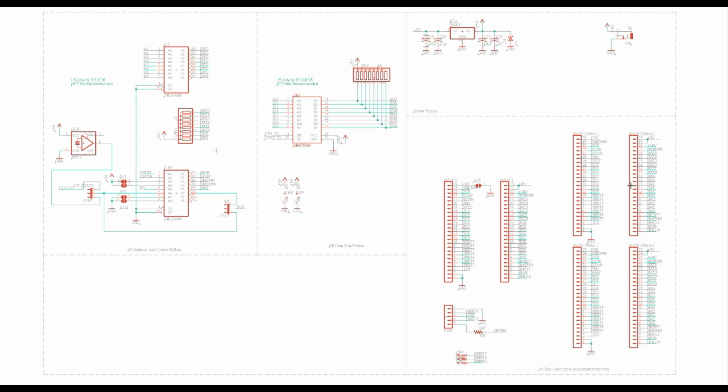Page 2 is the H8 bus. So this is the H8 connector over here. There's only one pair of these in reality, but there's 3 different footprints, so you see 3 sets of them. We've also got a connector here for the front panel. There's a 74 HCT 640. So all of the lines on the H8 bus are inverted logic. That's kind of unique to the H8. So what we need to do is we need to take those ID0 through ID7, that's our I/O data bus, and invert it when putting it on the H8 bus. So that's what this buffer here does. Similarly, we need to do that with the address lines A0 through A7, invert them.